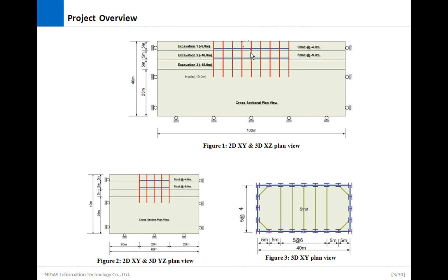So this is a very important feature when it comes to real-time geotechnical projects, because in that case the ground is not dry, so you need to take care of the pore pressure that exists in the ground. So you need to perform a dewatering analysis. In short, you need to perform a semi-coupled analysis. So here I am with the solution.